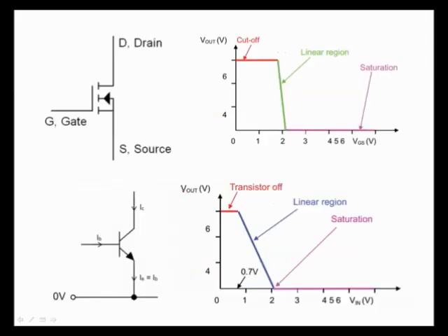If we look at this component here, this is called a MOSFET. So you need to know this symbol, and you need to learn it. You need to learn the 3 connections to it as well. But we can look at this, and this is our NPN transistor, and we know that it's got quite a long, or quite a big section between switching on and off. So this is a bit like using a dimmer switch to switch on a light source. I can turn it and the light gets lighter and lighter until it's fully on.